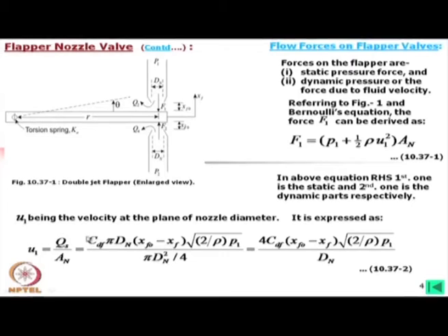While we are calculating this flow, as I told, we will consider this curtain area. So, this is the curtain area into 2 by rho into P1 under root, as the other pressure is 0. So, we consider the P1, whereas An is the area of this hole. So, this is pi dn square by 4, where dn is the diameter of this nozzle opening, and if we equate further, we will arrive at this expression.